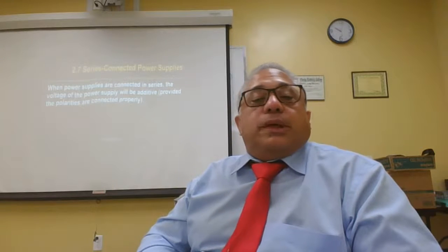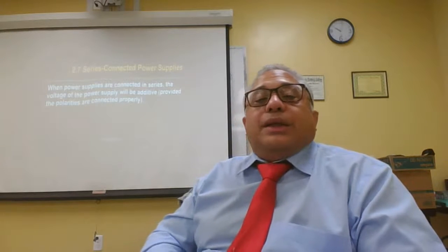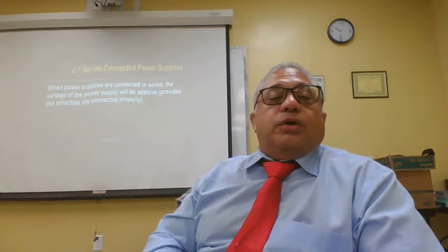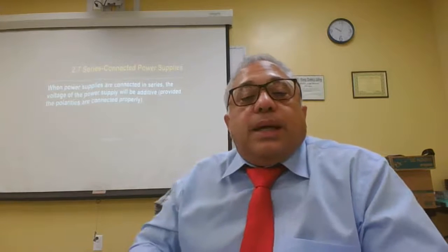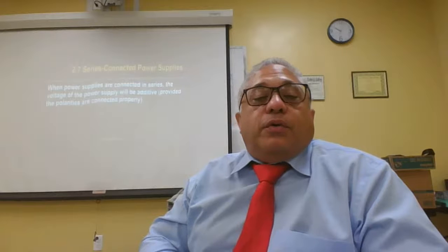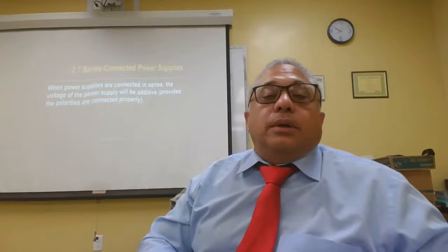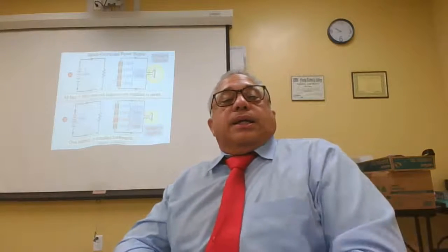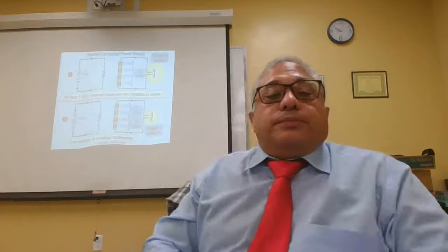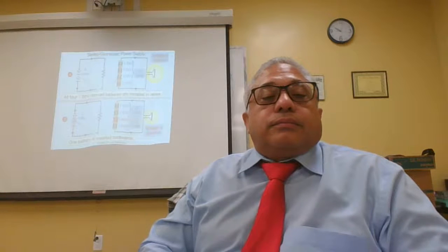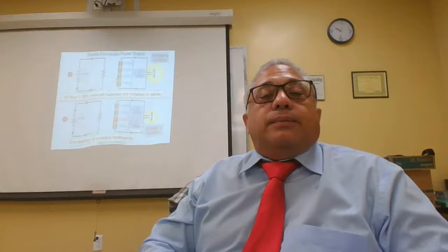Series connected power supplies. When power supplies are connected in series, the voltage of the power supplies will be additive, provided the polarities are connected properly. Series connected power supply. Here we have a 6-volt battery feeding a lamp.